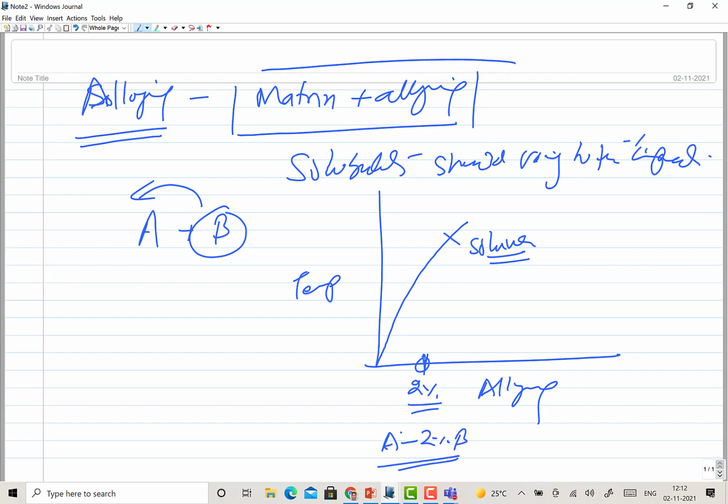Okay, so here it will have certain kind of precipitates, phases, compounds, whatever it is. When these are heated, you will find that these will tend to get dissolved completely after reaching a certain temperature as per the composition. So for 1%, say above this, all the alloying elements will be able to get dissolved. And so the temperature above which all the alloying elements will be dissolved in the matrix is indicated by this solvus line.